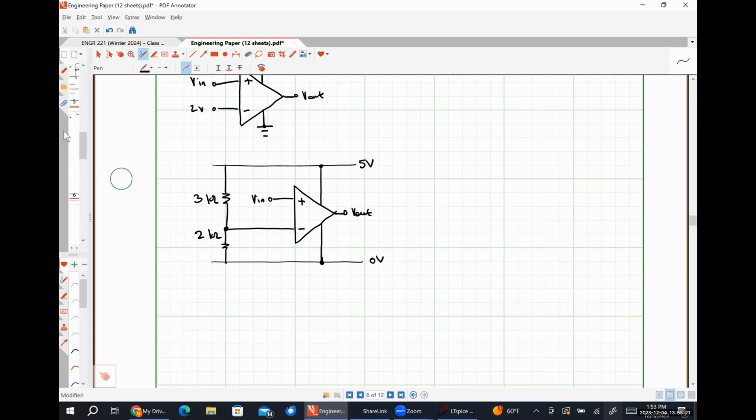So when there are 3 resistances and they're equal to each other, to go from this delta configuration to a Y configuration, you simply divide the resistor value by 3. So that's why these 10s look like 10 thirds. So effectively what I'm doing is I've subdivided this network in between these terminals X, Y, and Z, and I'm replacing it with an electrically equivalent network between X, Y, and Z. And then you get this.